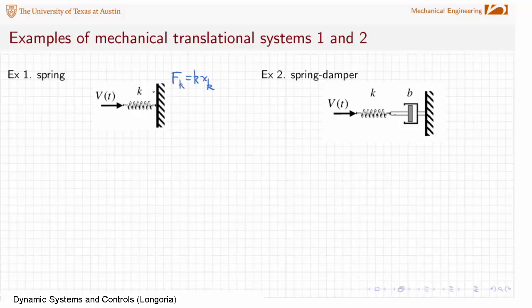We have an input velocity, so a very simple system. Again, the point is to illustrate the use of constitutive relations and derivation of state equation if we need one. So do we need a state equation? Well, let's say, to illustrate, say we wanted to find, what is the force on the wall here that spring is applying. Since we're applying a velocity, in order to find that force on the wall, we know, because this is an ideal spring, that the force on the wall is equal to the force on the spring.